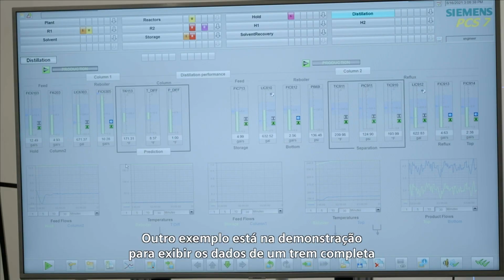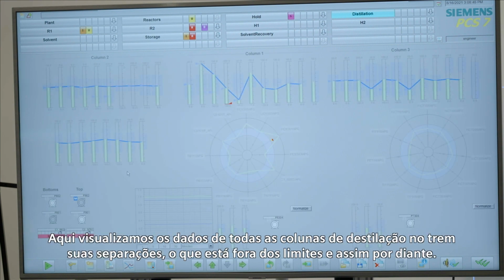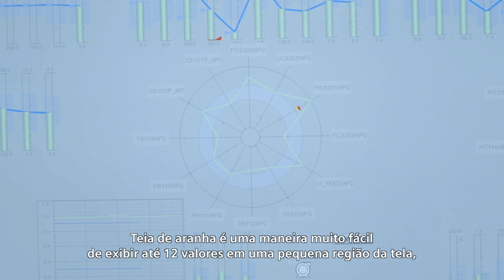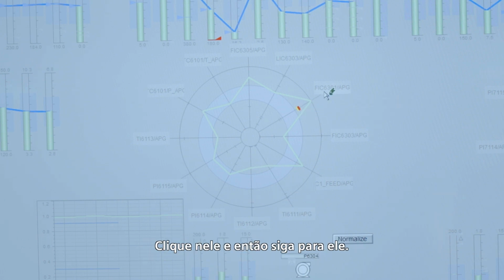Another example in the demo shows you the data of a complete train. So this shows the data of all the distillation columns in a train, their separation, things that are out of bounds, and so on. And what we do in this picture is, what you see here is spider webs. Spider webs give you a very easy way to show up to 12 values in a small piece of the screen, with the ability to immediately conclude that a value is out of bounds, click on it, and then jump to it.